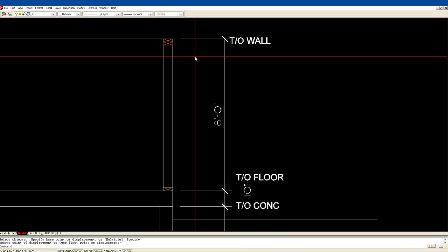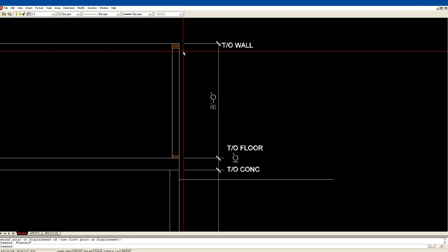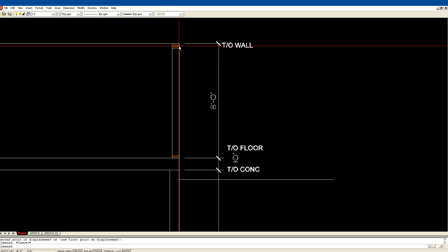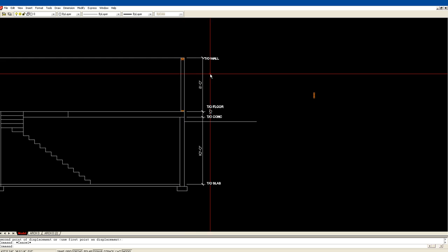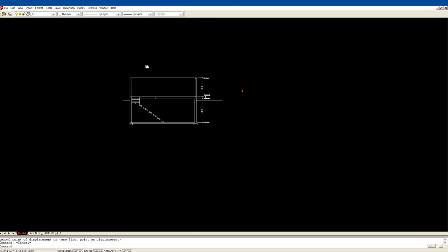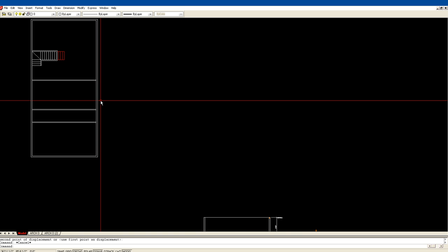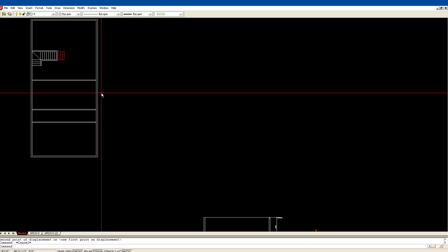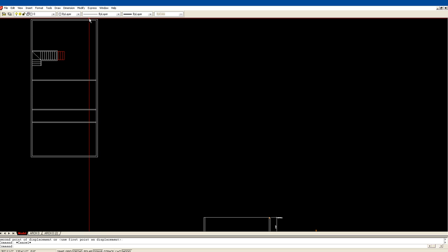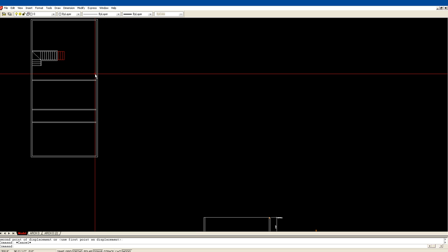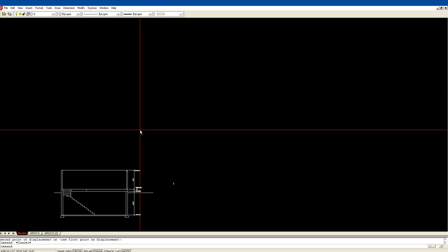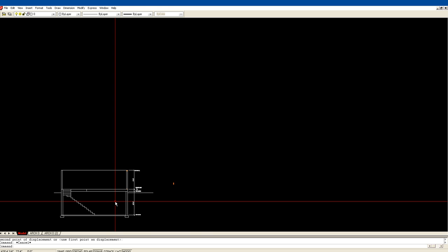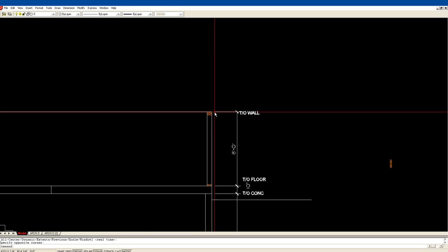Okay, again, this is a cross section of the wall. So we have two plates at the top. Typically, when they're building this long wall here, which is the one that I'm showing the cross section of, they won't build it 58 feet long and try to stand it up. They'll build it in sections. Okay, maybe break it into 3 sections, depending on how much manpower they have. They will join the sections together with this, what we call locking plate at the very, very top.